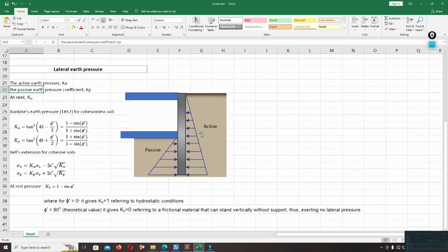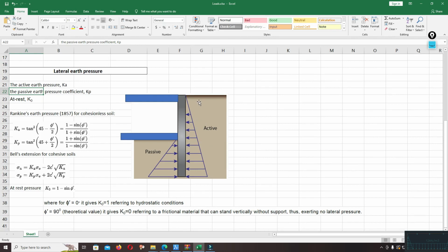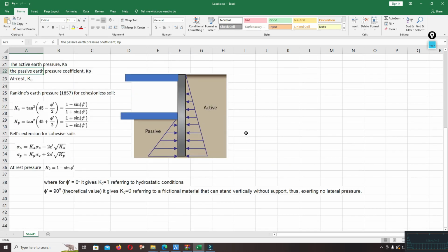And for the pressure, we also include the water pressure. So you must check the water table at the ground floor, where the water table is present. The depth may be minus 4 meter, 6 meter or 3 meter. You must include the water pressure applied on the wall. For the gamma soil, we should use gamma saturation to apply the water pressure and the earth pressure on the wall. We use gamma saturation. Do not use gamma dry to calculate the earth pressure on the wall.